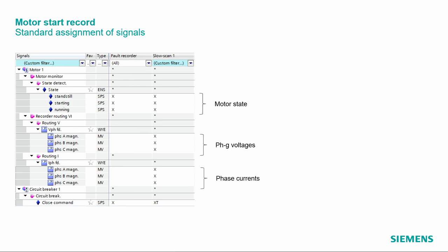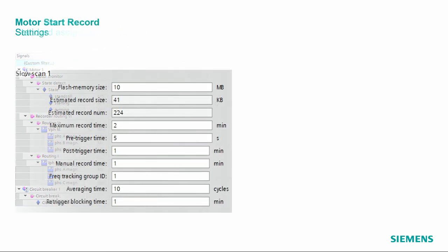There's also continuous recorder and a trend recorder in all Siprotec 5 relays available now in the protection relays, just to mention that if you did not know that. And the reason why we did this was also triggered here for the motor protection, because we wanted to have this motor start record or log, basically, that we can register what happens during the motor start.